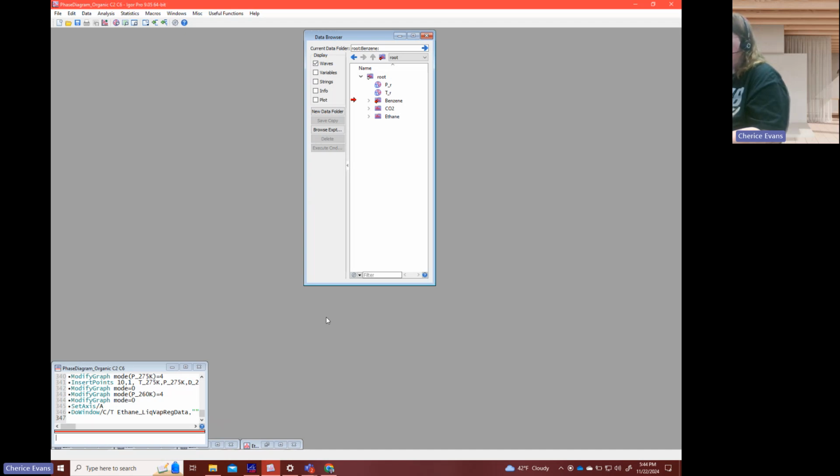It's usually a very complex equation of state, with somewhere between 50 and 100 something parameters. And it's designed to fit to fairly high accuracy, which means less than 1% error in the pressure, temperature, density range that they provide for you for whatever equation you are looking at.